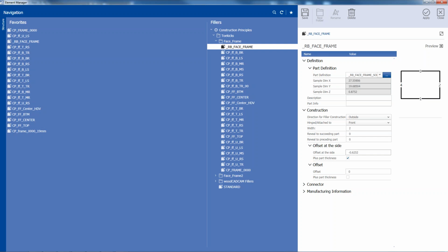Oh, so those numbers, I'm assuming, will always be rounded to millimeters? Because I'm pretty sure I put in 0.625. Yep, it says 0.625. What was the question? If this number is 0.625, I know it's a minor difference, but will it always be overwritten and rounded to millimeters? No, what it does is it rounds it to millimeters and then rounds it back to inches, but you'll get the 625 on your cut. When it cuts it out, it'll be the 625.